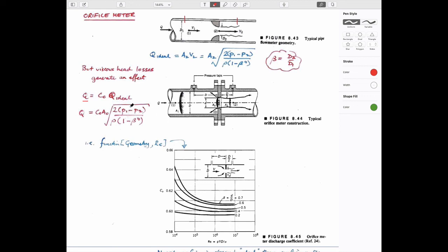And ultimately, if you can measure the pressure drop between these two locations, if you know what the density of the fluid is, if you have some correction factor that says something about the geometry of this orifice and how it departs from ideal conditions of an inviscid fluid, for instance. Ideal means viscosity equal to 0, is what we're calling ideal. In other words, the requirements for a Bernoulli equation are that it's an inviscid fluid. And then you can calculate what this correction factor is as a function of the flow rate.